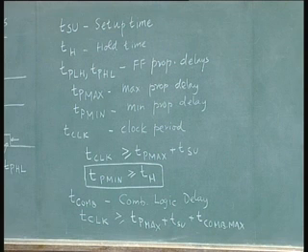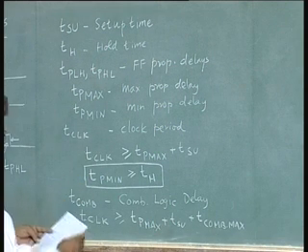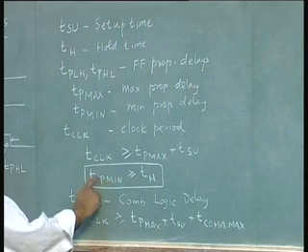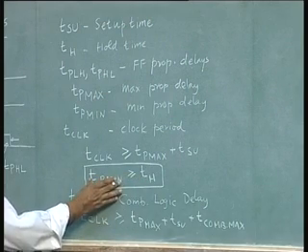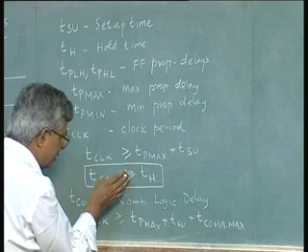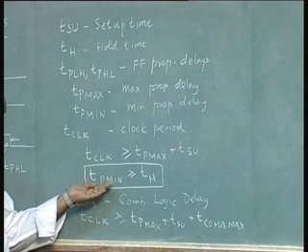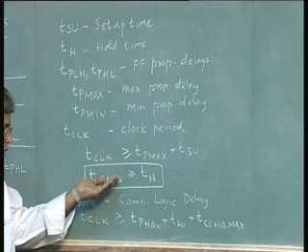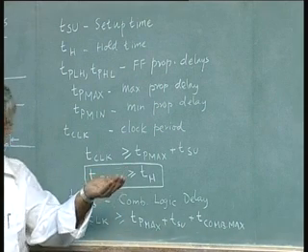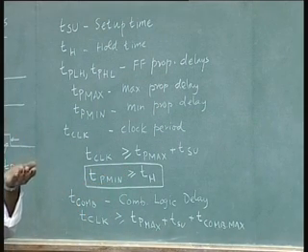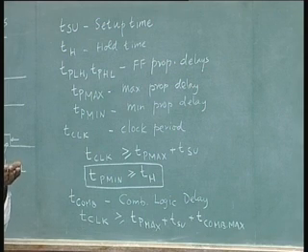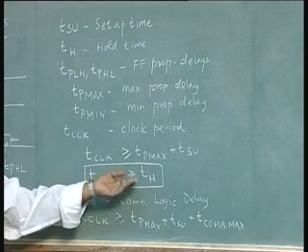And likewise this equation also will get modified as Tp minimum plus, so that means now this is an extra restriction, this restriction gets reduced a little bit because I have the extra combinational logic delay. What I said here was the propagation delay should be sufficient so that it does not reach the input in case of feedback before the hold time has expired.